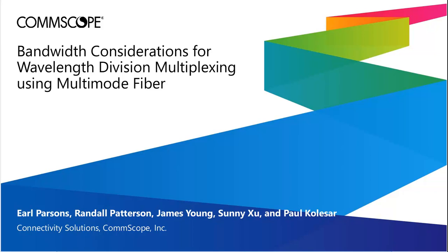So today I'm going to talk about multimode fiber. I'm going to talk about wavelength division multiplexing using multimode fiber. I'll emphasize which fiber parameters are most useful for predicting system performance when you have multiple wavelength channels, and also describe the difference between OM4 and OM5 fiber.